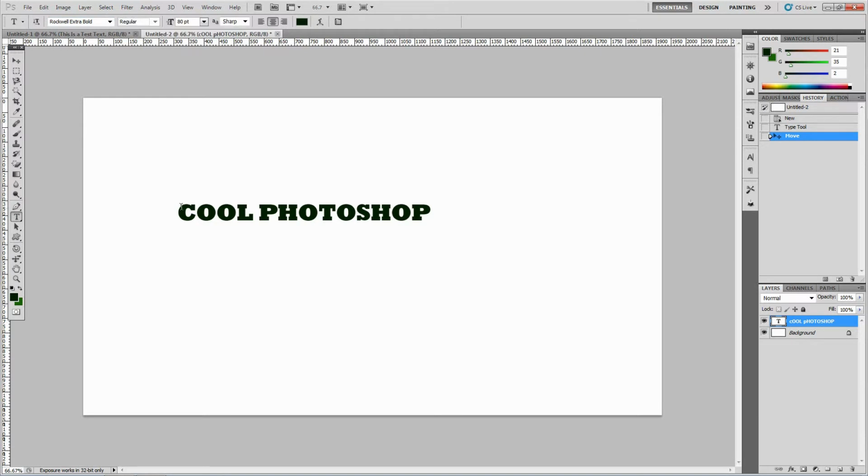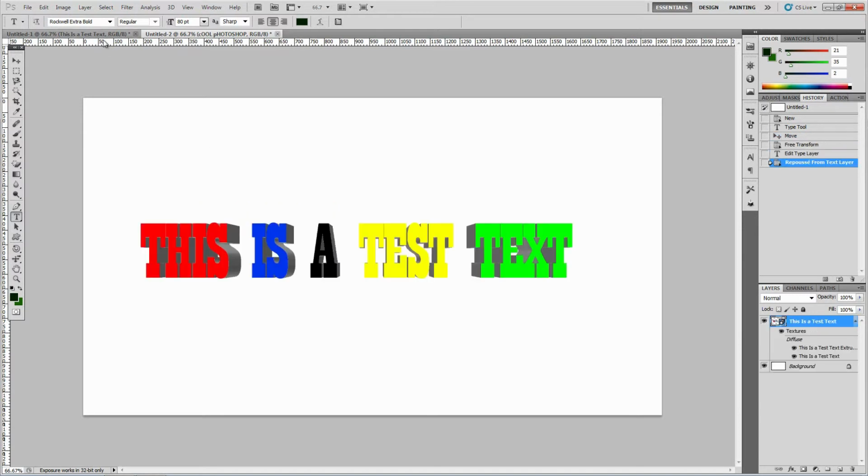You will see on the right side over here on the layers that I create a new layer for each word or phrase that I want to play around with afterwards. Don't put all the text in one layer, because let me just show you real quick. This is one text in one layer, and once you convert it into 3D, not only can you play with the words, meaning putting the text behind anything else, the extrusions will also come as gray. Okay, and you don't want that.